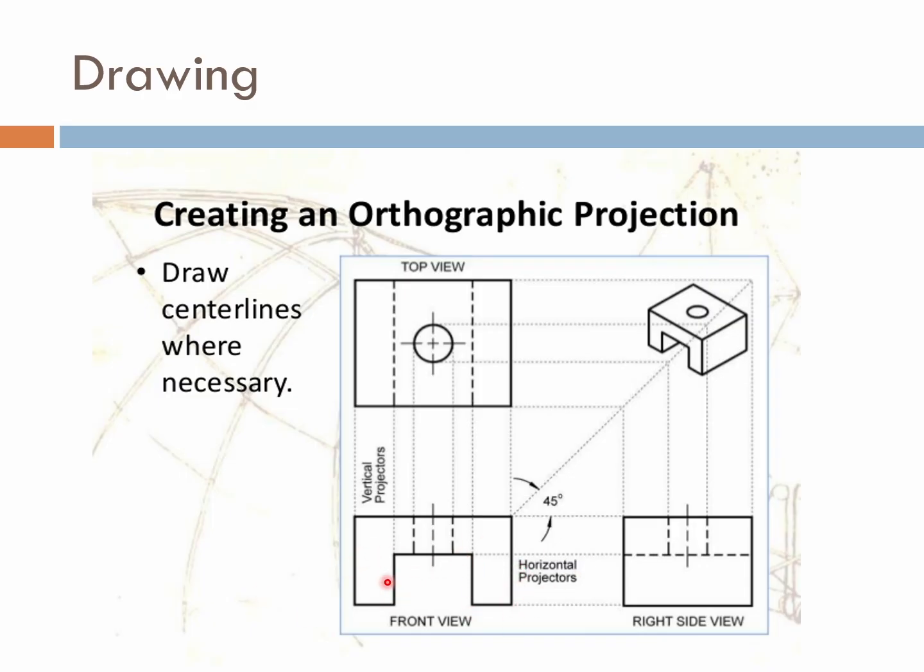Now, your next top view, you're not going to have to remeasure the width of it, because you already know what it is, because you just follow these lines straight up. That's your one edge, that's your other edge. So you know how wide it is automatically. Then all you have to do is measure across here to get this measurement. And once you do that, you have your basic information.